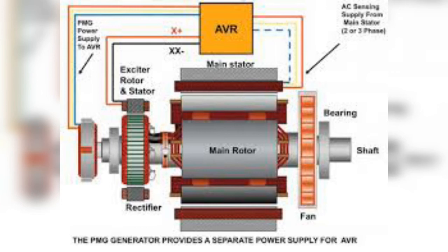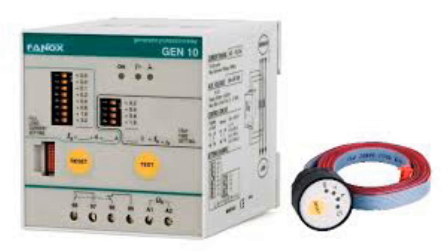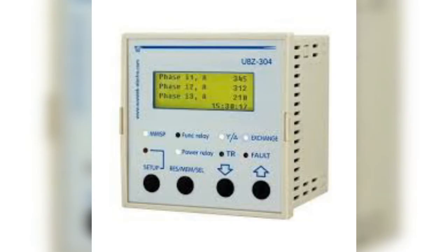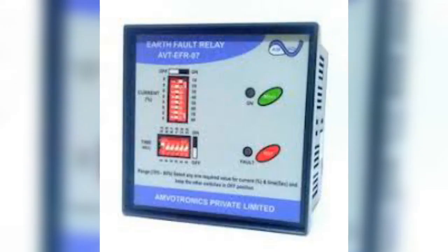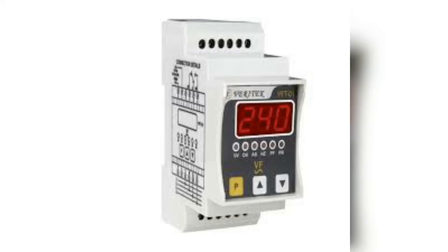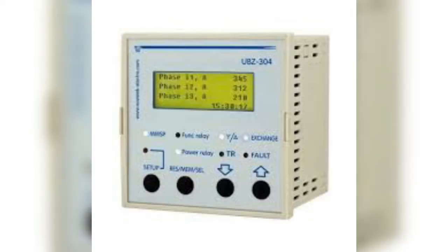And the most important topic about the generator is why generator protection is needed. Over voltage protection is required for hydro generators or gas turbine generators. Protection of a generator is also needed due to unbalanced load. Due to the fault, there is an unbalance in the three-phase stator circuit, and due to this unbalanced current, double frequency currents are induced in the rotor core.